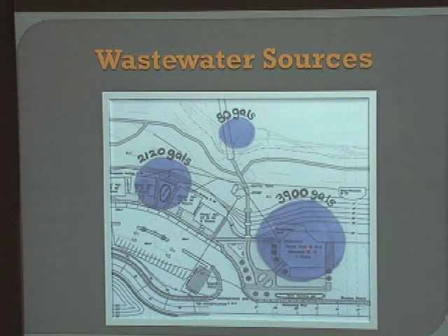Thank you, Adam. Well, to determine our sources of wastewater, we consulted both RIDEM's literature and CRMC to make sure that we were adhering to what we had to. First off is the restaurant area. We figured there was about 3,900 gallons a day that we needed to be able to treat from there. We based that upon 25 gallons per day per seat for dinner patrons and about 10 gallons for bar patrons.